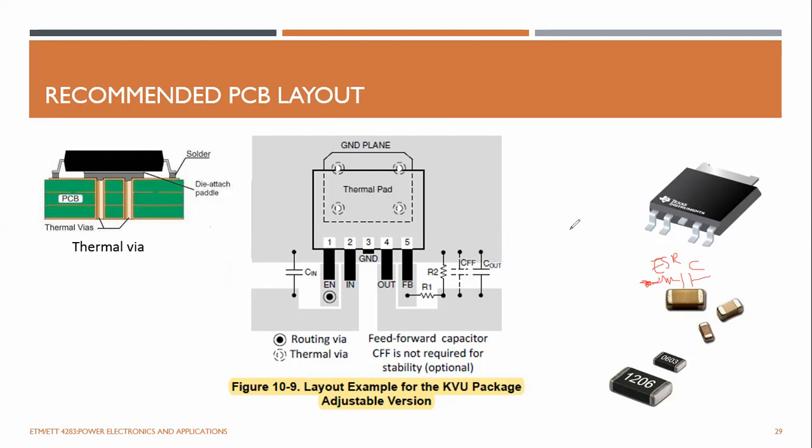But if you put this output capacitor somewhere here, far away from the device, close to your load rather than close to your device, what will happen is, this is connected via a PCB track. The PCB track has inductance and equivalent resistance, right? So you select this as one value from the datasheet, that is your stable ESR.